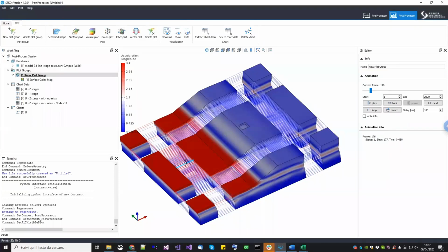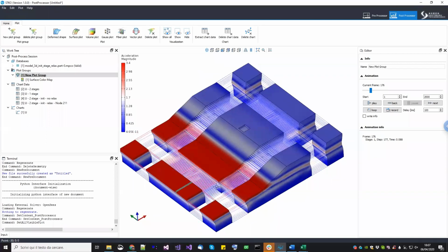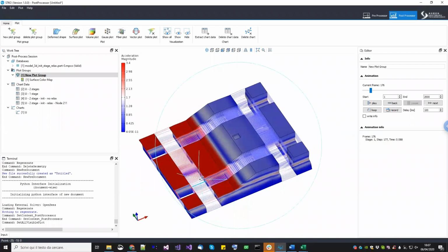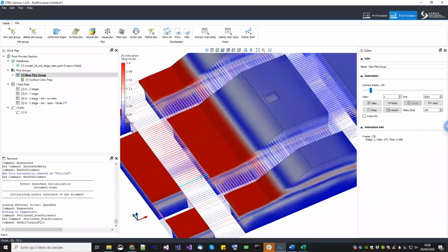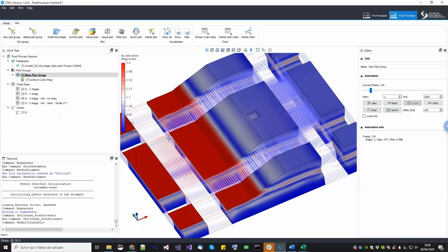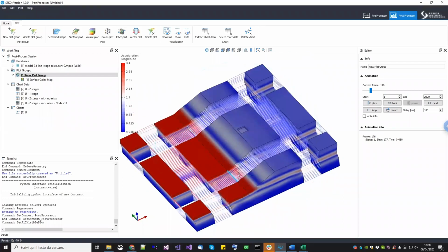So you will learn how to do this kind of model, how to do solid modeling, a solid structured mesh. Then you will learn how to use interactions to define equalDOF constraints for the free-field columns, how to create Lysmer-Kuhlemeyer dashpots. You will see that STKO has many features to create automatically distributed boundary conditions instead of a one-by-one lumped spring and dashpot. And then you will see how to do staged analysis.